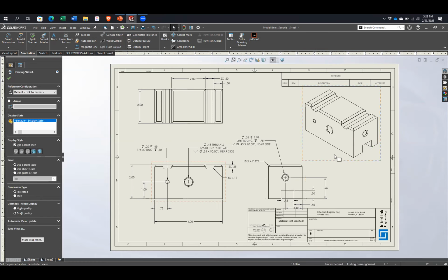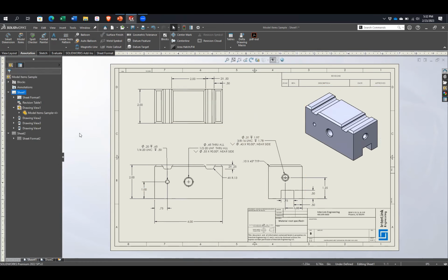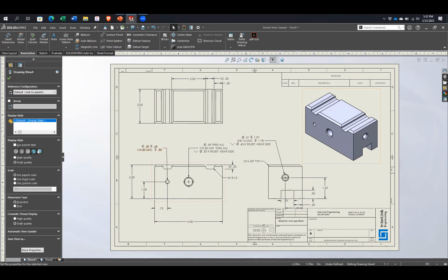It is very easy. You click on the view, and then if you click that button right there, that was easy. It's always nice to have SolidWorks make the hard things easy for you. So you can just select the view and change your shading, whether you want it with tangent lines or without. And you can do hidden lines as well.